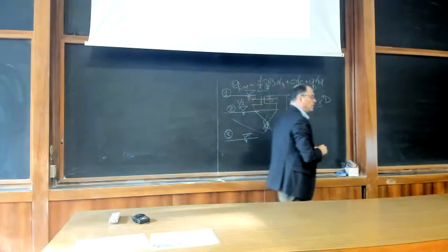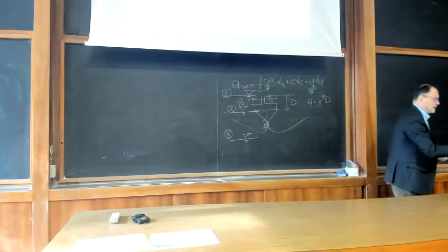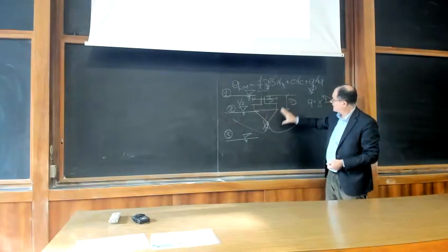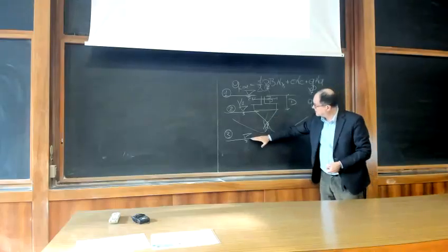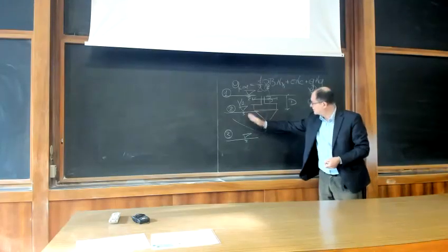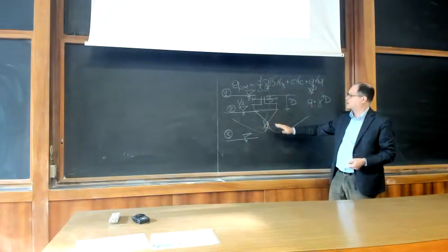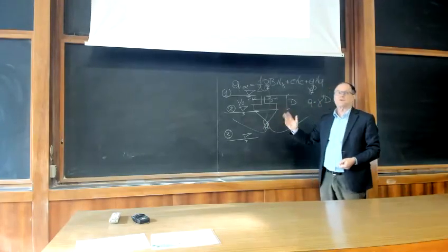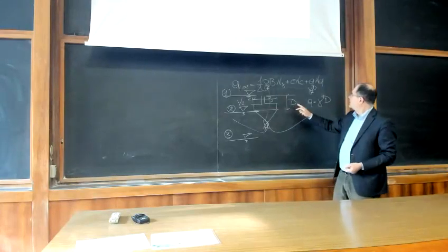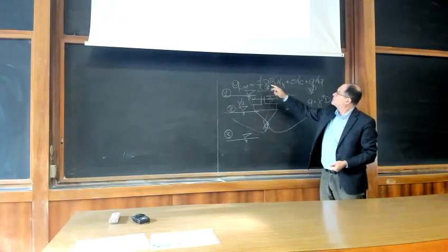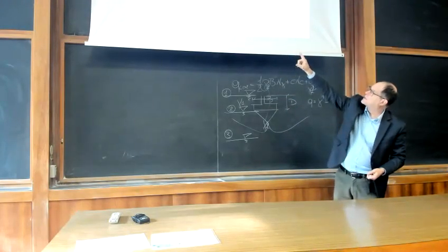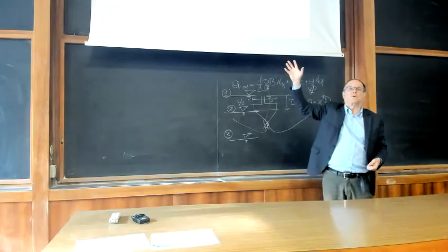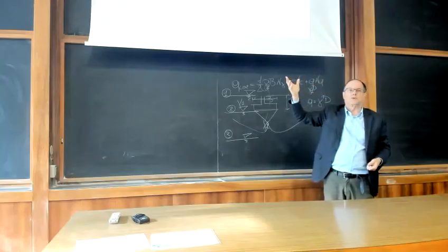So, for example, if you have the groundwater table which is deeper than D plus B, this does not affect the failure mechanism, and so you can consider that there is no effect of the groundwater table. Now, why is it so important? Because, for example, your gamma dash is the gamma saturated minus gamma W. So gamma dash is more or less half than the gamma saturated.